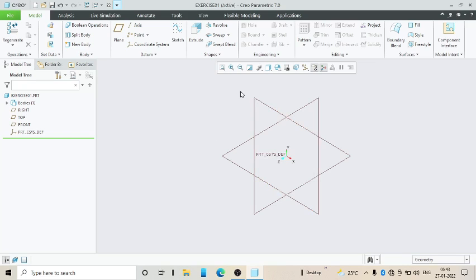On the 3-button mouse, the left hand side button is the left mouse button, and it is used for selection. And MB2, that is the middle scroll wheel, it is for rotate. You press it and move the mouse for rotation. Then the right mouse button is for filter or query selection. So that means if you want to select something, multiple selection and all, you will get some options there.